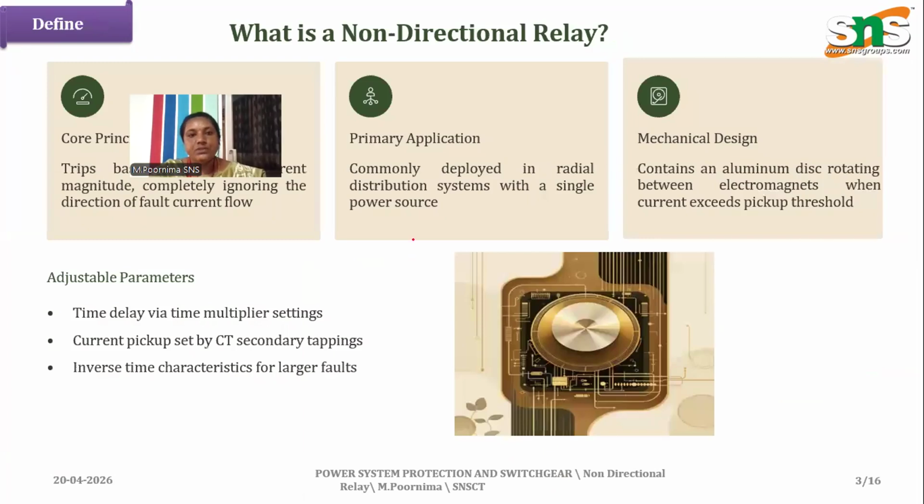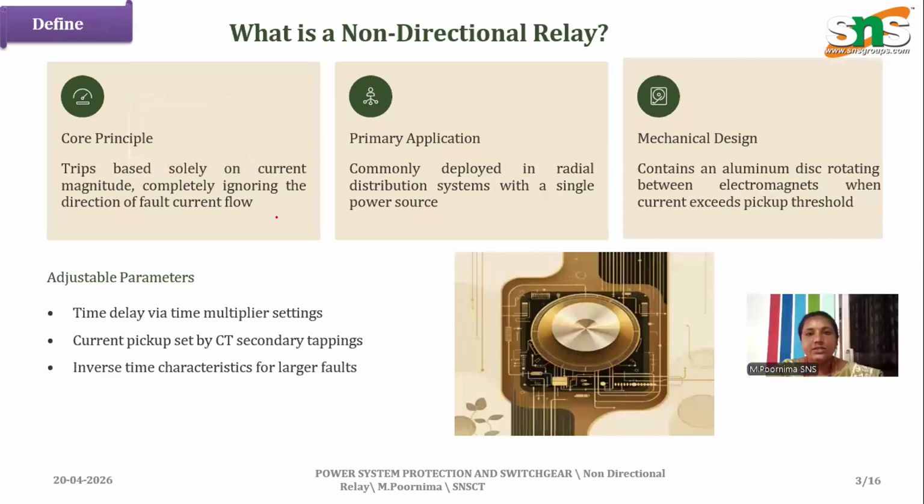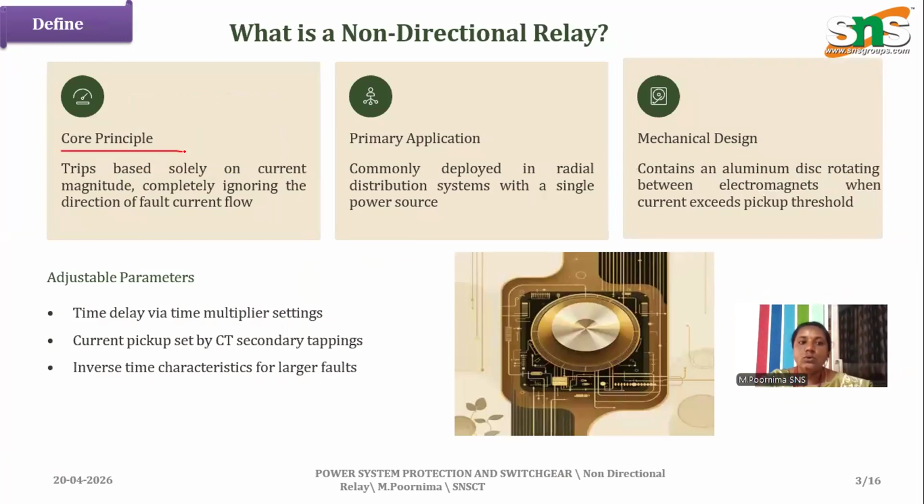Now coming to why the non-directional relay is needed. What are the core principle and primary applications? It is based on mechanical design and has adjustable parameters. It trips based solely on the current magnitude, which ignores the direction of the fault current flow.